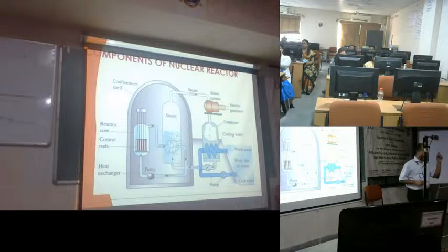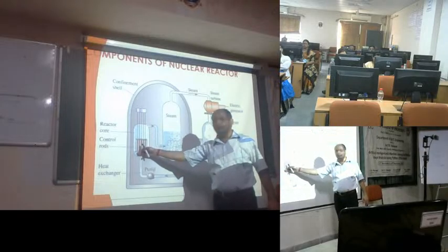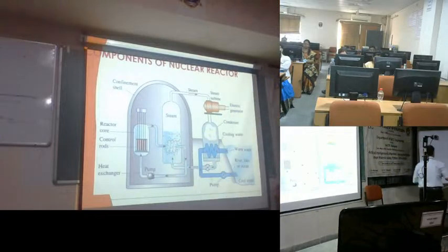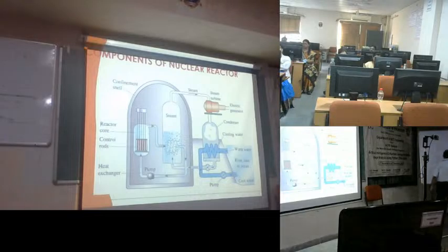For example, if I need to control only a little neutron, I will not insert the control rod fully, I can only half immerse it. This metallic string will be pulling the rod down. So maybe one rod is fully immersed, one is half immersed, one is this much immersed. It is an automatic process, depending on how much power demand has come; the demanded power needs to be matched with the actual power, and accordingly this algorithm works and the level of immersion of the control rod gets regulated.